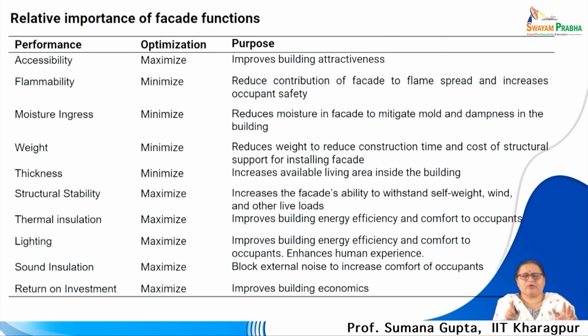So, the relative importance of the facade function has to be known. So, we have to optimize accessibility, flammability, moisture ingress, weight, thickness, structural stability, thermal insulation, how much light it is allowing, how much sound insulation it is doing, and also the return on investment, which is the money part, because every material has its cost.